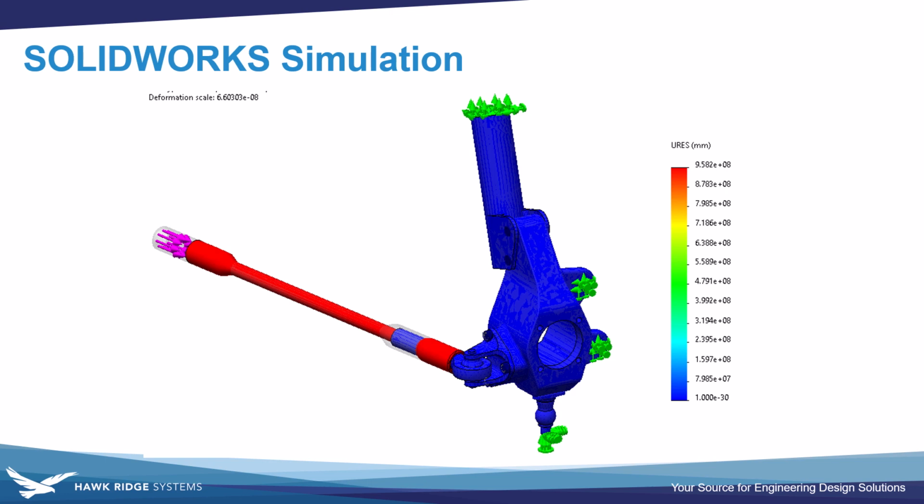So you want to be sure you're on automatic deformation scale, and this will scale down the deformation so you can actually see which body is under constrained. If you were to go to true scale, you'd probably see this body fly right off the screen. So this is a fallback method you can use to stabilize the problem to try to visualize which bodies are under constrained.